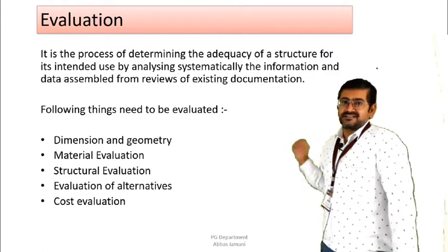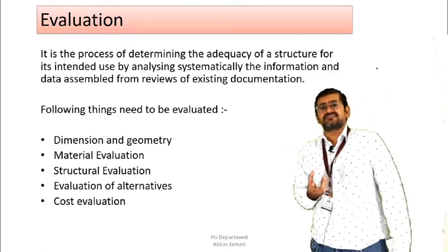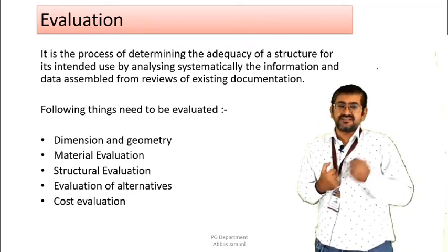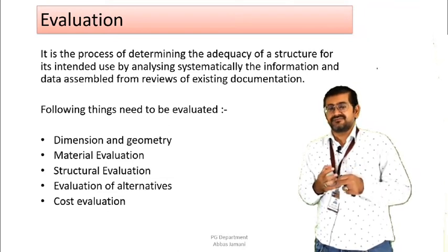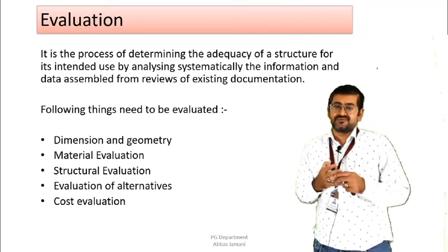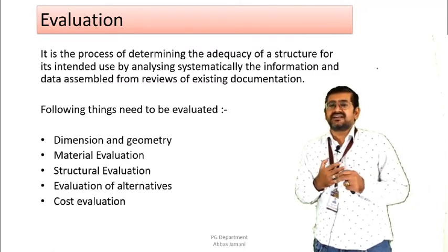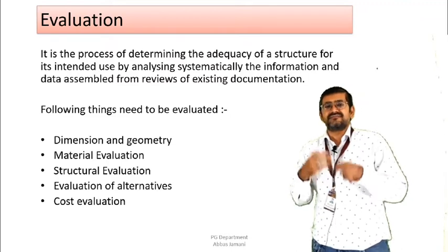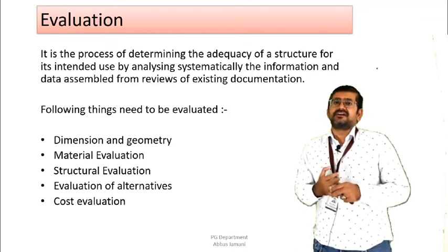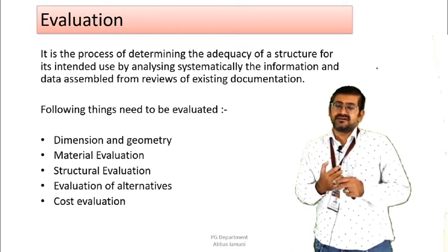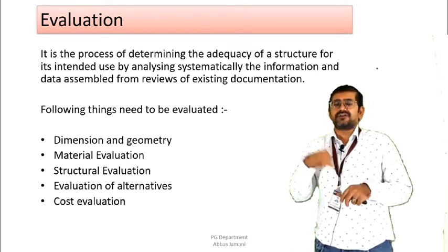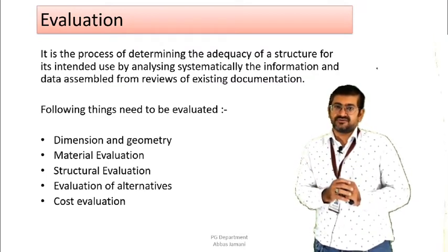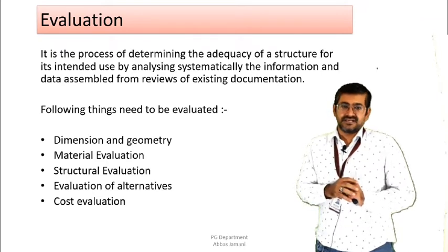Right? Then structural evaluation. In case of structural evaluation, you will need to check whether the structure is capable of undergoing this change or not. This evaluation can be done in three forms. First, you do only an analysis model. That is, for example, you carry out the analysis using FEM or some other kind of model. Second, you also prepare a physical model. And thirdly, you check with respect to the provisions of the current code. After doing all these three evaluations, you will be able to decide whether this structure is capable of undergoing these necessary changes or not. So that is why the structural evaluation part is there.